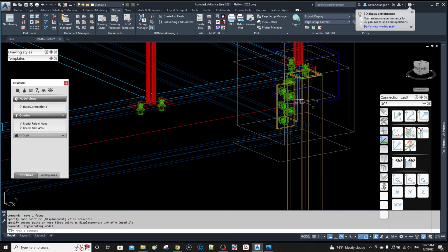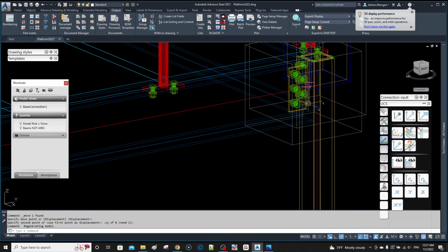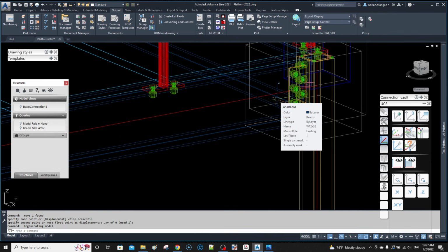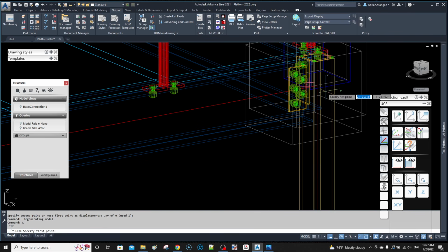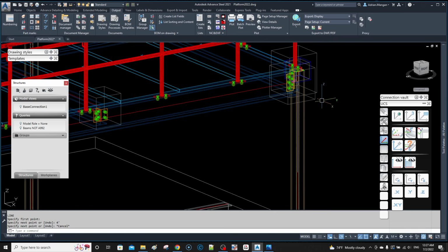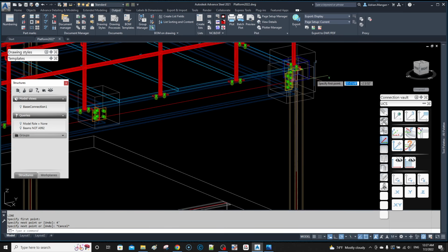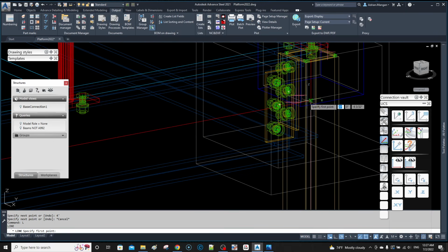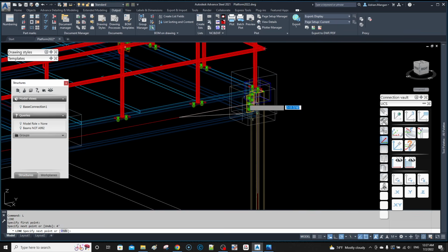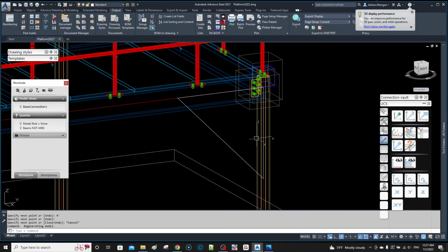So now this is the only time I ever switch the system line from the top. So I'm going to draw a line. I'm going to come down 4 feet, usually 3 feet, but I'll do 4 feet. Let's do 4 feet, and then I'll come over 4 feet. I'm just going to put in a single brace. I'm going to draw a line there altogether so I'll know where the brace is going to be. So that's where my brace is going to be.